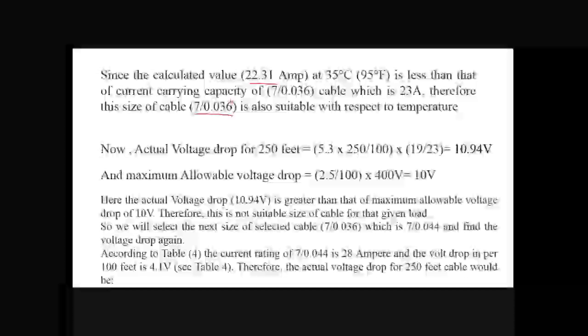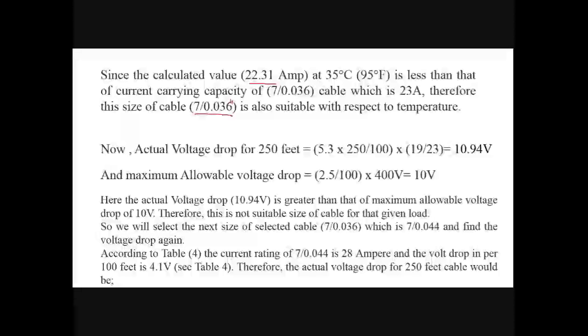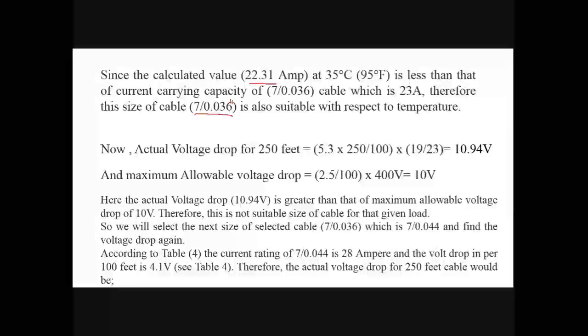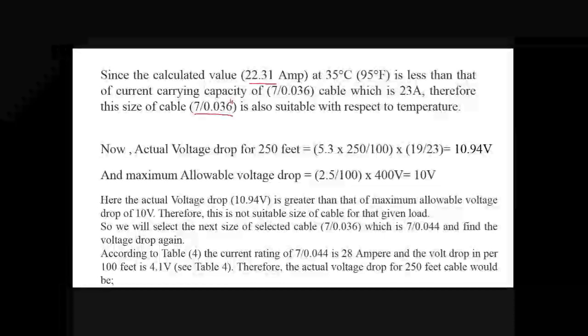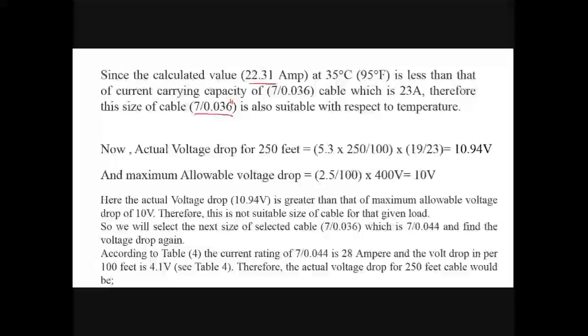So far we have seen that with the help of current and temperature, we have found that the 7 divided by 0.036 inch cable is suitable. Now we will go ahead.